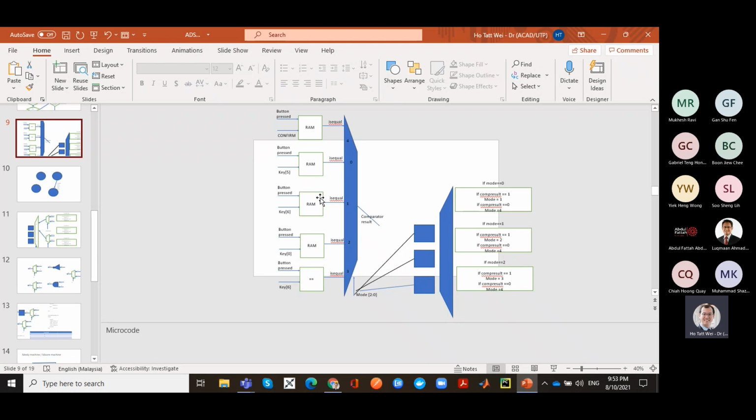But I'd like to broaden your thoughts a little bit more, right? So we've talked about the programmability and how you could use that to implement different computational operations in the mode that is in the data path. But then you realize that even the selection of the mode is a combinational logic followed by flip-flops. Therefore, I can also program this part here.